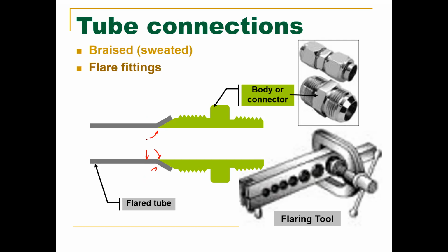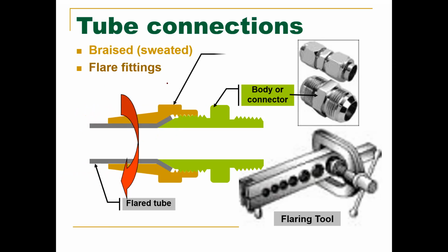The tube, let's say, is 3/4 of an inch. This flare might go all the way out to an inch. Right? And we're not adding any material. We're flaring it out. We're pushing the material, making it thinner. And the only thing that is sealing on here is basically these two things. We have the nut and the body connector. So it's utilizing the material to be the sealant. These threads, as it pushes this force downwards, it makes a seal here and here.